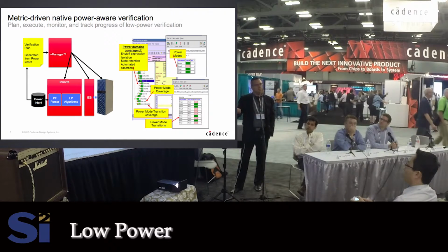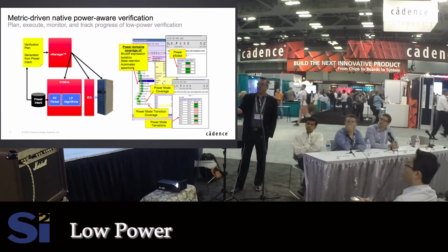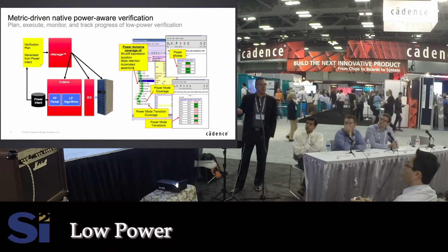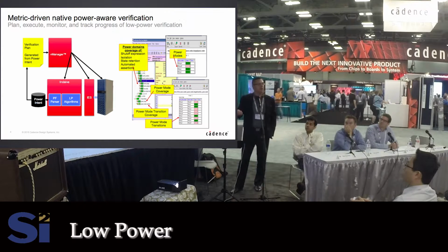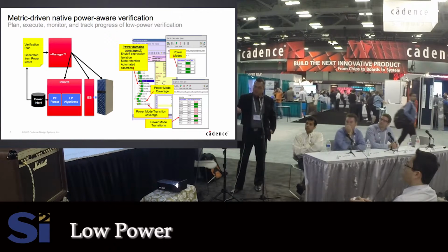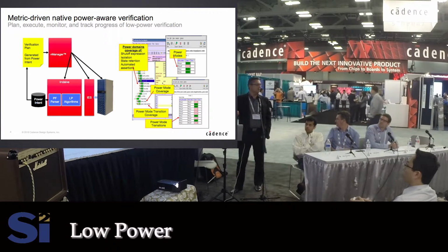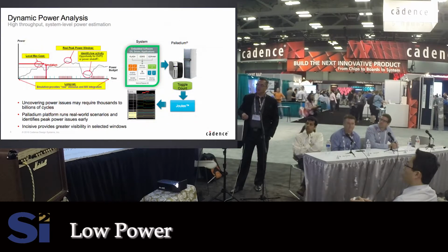And then we're dealing with fun effects here, where you're now so accurate in modeling this power shutoff that you end up having effects like the software guy complaining the hardware is not taking their inputs by programming registers. Well, when you verify, it turns out the item they want to actually write into has been just shut off, and these mechanisms actually are modeling this fairly accurately so that you can get these hardware-software effects under control.